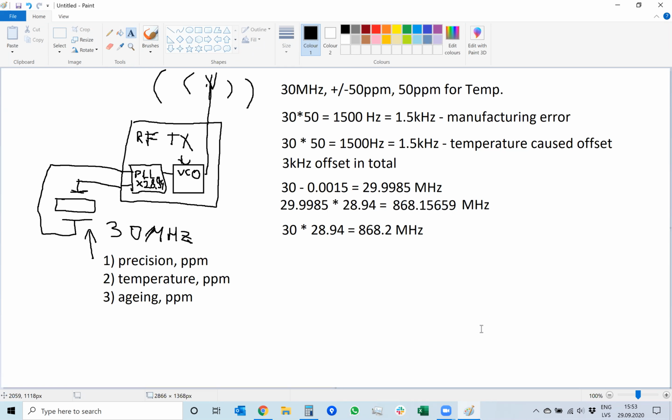And if, for example, we have a very small deviation, then the signal looks like it's even maybe on another band instead of the band that we need. Okay, so the difference doesn't look that big yet. So this is our reference. But let's say that the transmitter is, for example, hot, and we picked accidentally the slowest crystal.